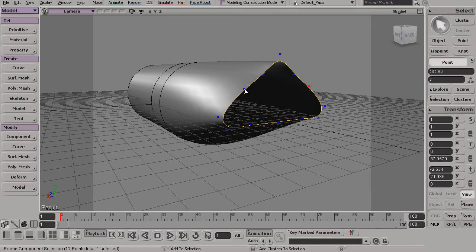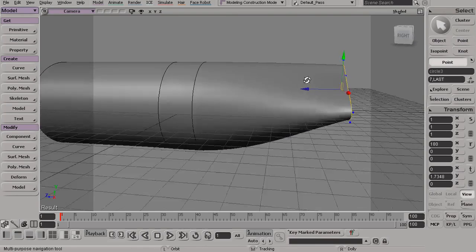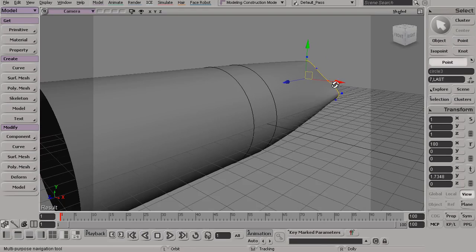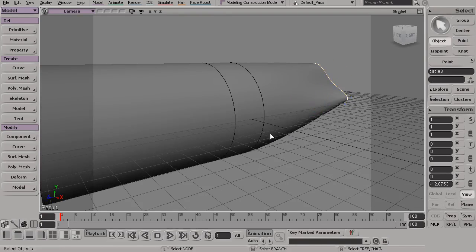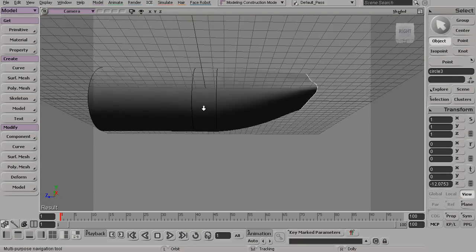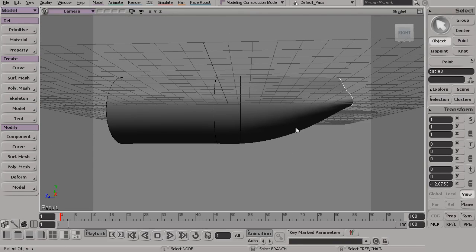All right, and again, just a matter of coming in here, grabbing a few of these points here and there. I'm just trying to shape those in a little bit more. Again, maybe press the X key on my keyboard to scale those together and sort of pinch those together. Okay, now that starts to slope this piece of geometry from this kind of back curve up to this new curves that we just reshaped.